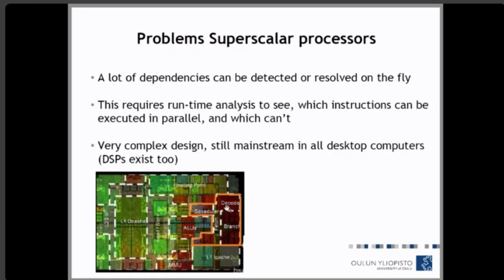Then there is another interesting thing here, that you see this large area for floating point. If you use fixed point operation, that's gone. We get rid of that. So you see that a large area is dedicated for caching, instruction caching, scheduling, and that hardware can be used elsewhere.